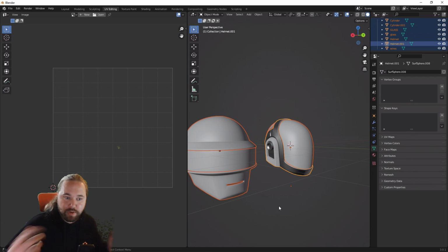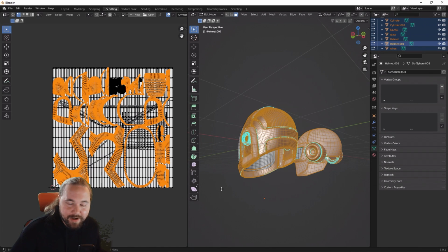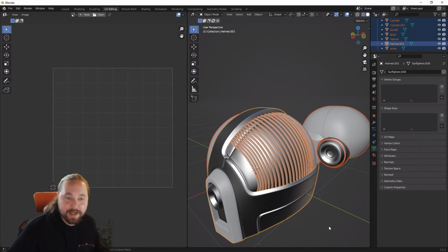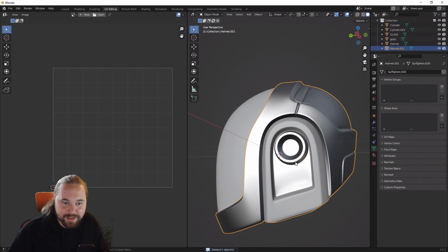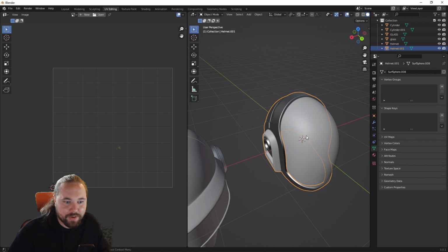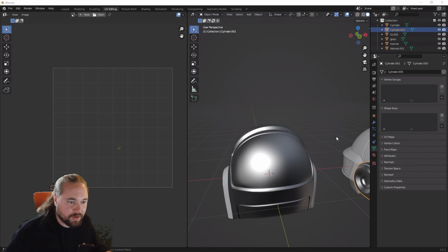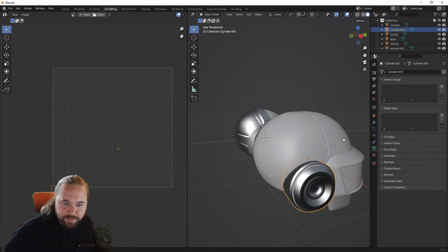One of them is to simplify the models we have. Once again, those are 120,000 polygons right now. So I don't care about the detail in my design application. So one thing that I'm going to do is select those and delete them. I'm going to select pretty much everything that's not important for the overall shape and just get rid of it. So let's see. Do I want to keep those ears?